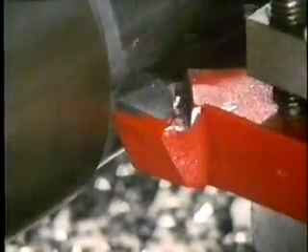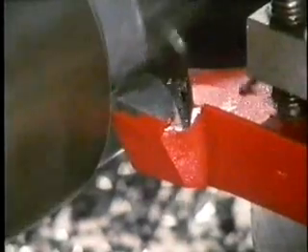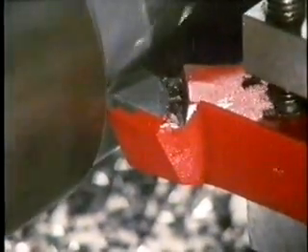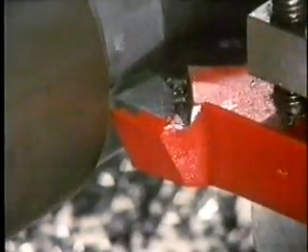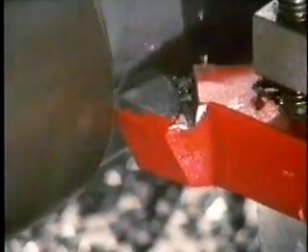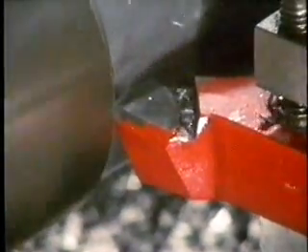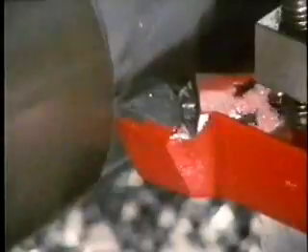For machining hard and brittle metals like cast iron and cast bronzes, which have a highly abrasive skin and produce short chips, a specialized cutting material is needed. The carbides of certain metals, notably tungsten, are extremely hard, but not tough enough to stand up to the rigors of the metal cutting process. In the 1930s, it was found that these carbides could be bonded together by another material, cobalt. The result was a cemented carbide.